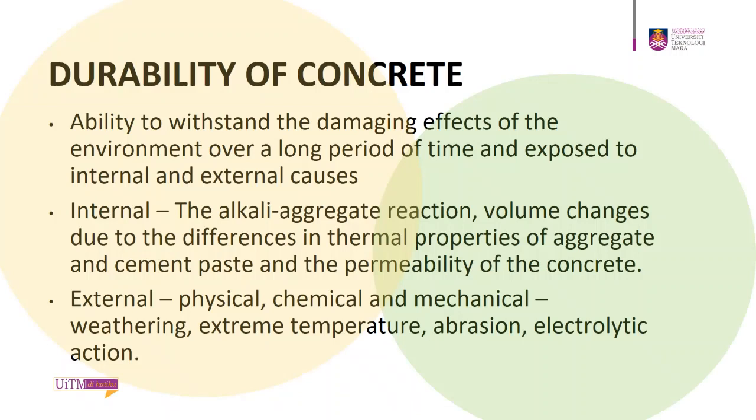Next is the durability of concrete. Durability is the ability to withstand the damaging effect of the environment over a long period of time and exposure to internal and external causes. The internal causes are the alkali aggregate reaction, for example, the volume changes of the concrete due to differences in thermal properties of aggregate and cement paste, and the permeability of the concrete.